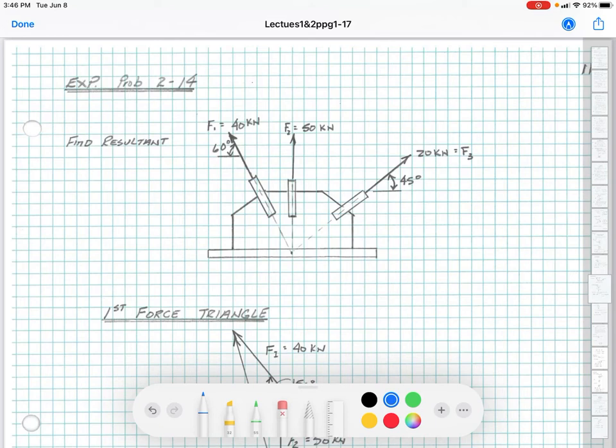Now, as you get through what this could be, for example, this could be like a foundation here, and this piece here is a base plate that's anchored in with some anchor bolts, and then this gusset plate here is welded possibly all the way around to the steel base plate. So that's how the load is transferred down into this foundation.